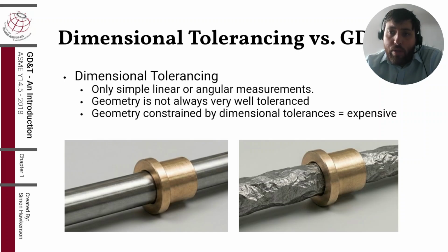Even if you don't care that much about the diameter of this shaft, you should still be concerned about its cylindricity. Even if the shaft fits through the hole, if it isn't round, it will cause vibration, it will cause uneven wear, and it will destroy the oil film wedge needed for that lubrication.